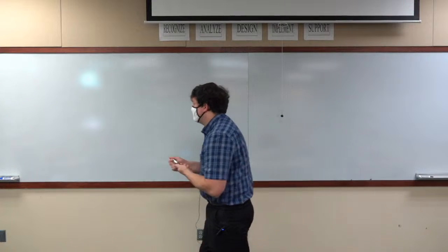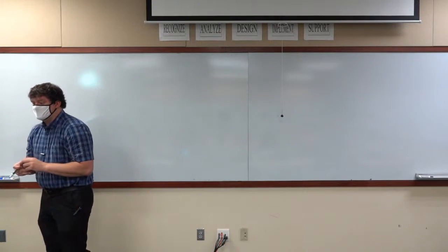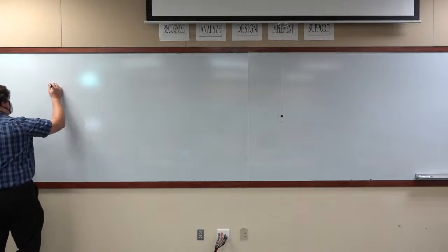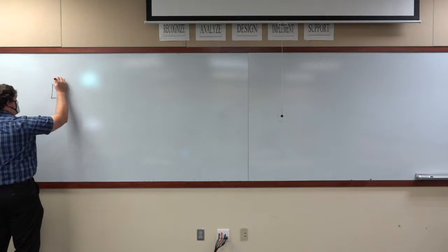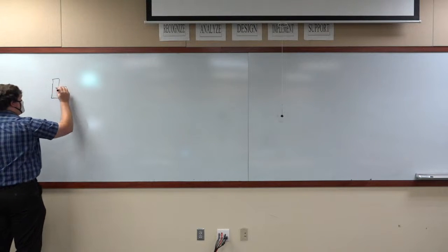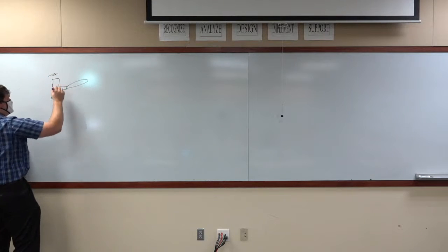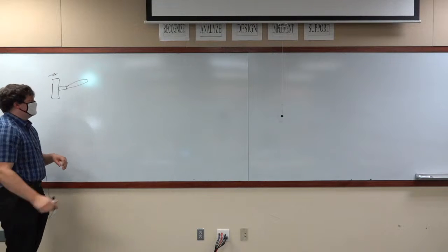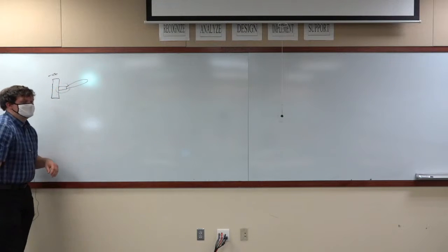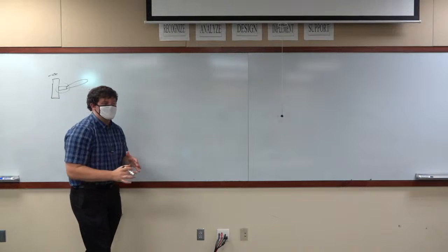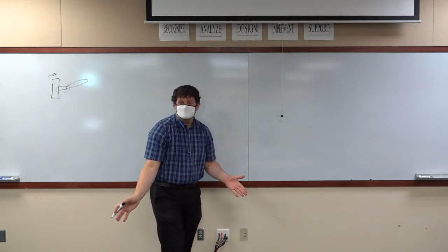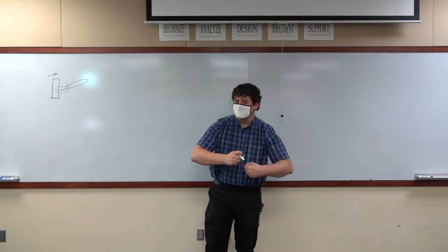Say you've got an element that has a linkage here, and it's being driven forward and backward through a crank motion. And you specifically design this linkage so that if it is carrying more than 2,000 pounds of force, it just breaks.